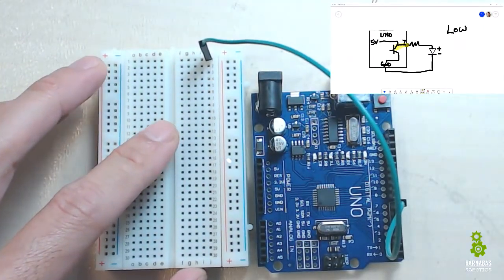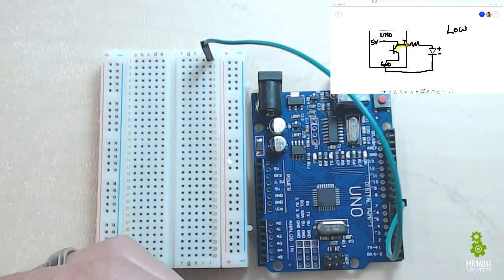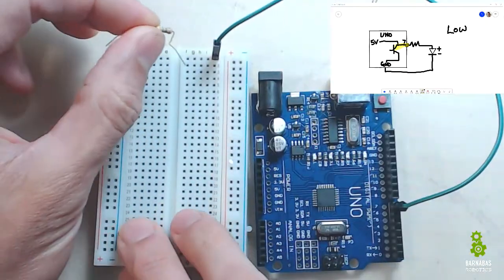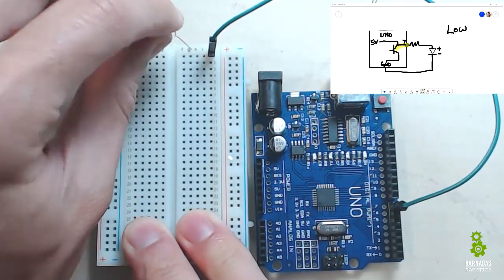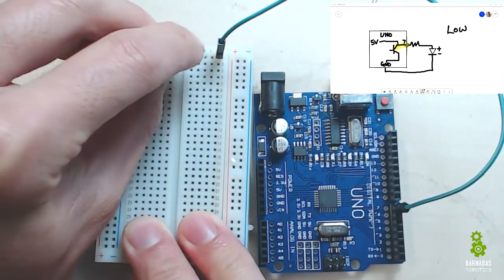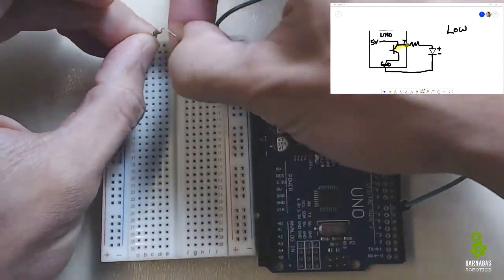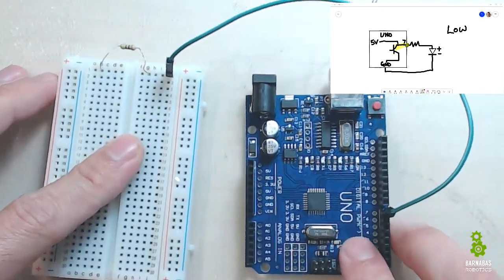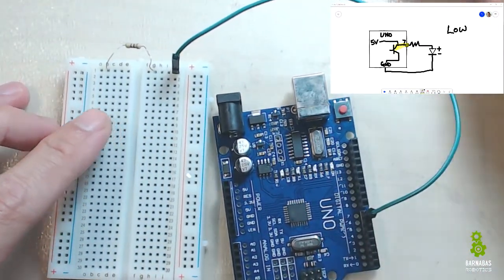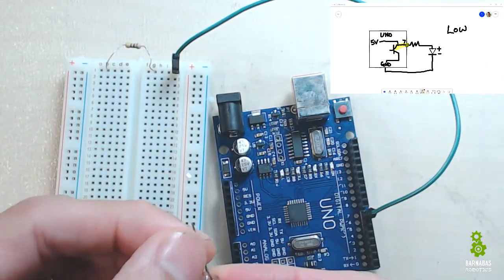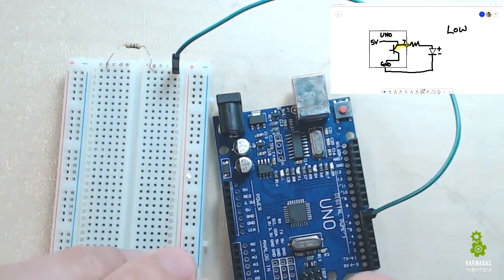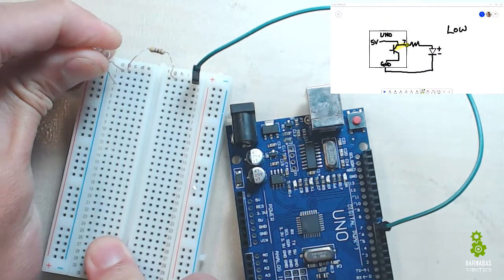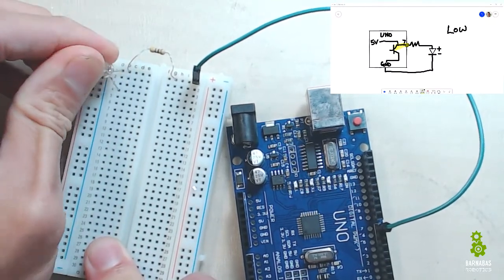All right. And then I want to connect the resistor to that row. And then the other side of the resistor, I'll go to the other side too, because I'm going to make a new connection later. Let me fix this here. Okay. Alright, and then I need my LED, so I'm going to grab one of my LEDs. The long side connects to the same row on that new row I made, and then the short leg will go somewhere else to a new row.